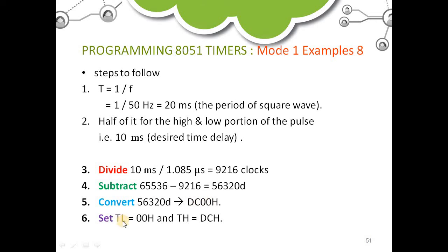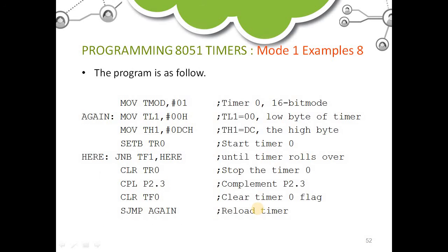So if we look at the programming part, TMOD register is loaded with 01H, which says the timer 0 and mode 1 configuration. And then next we will be loading the TL0.